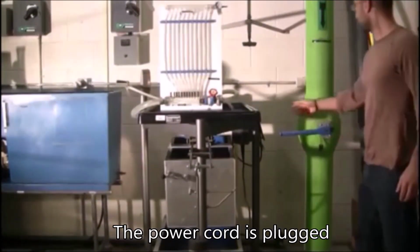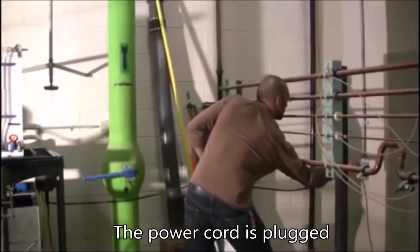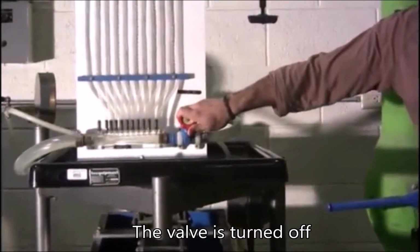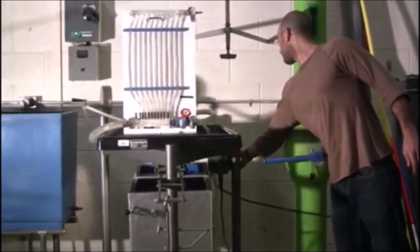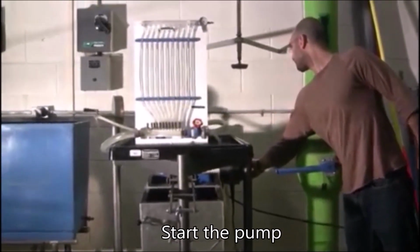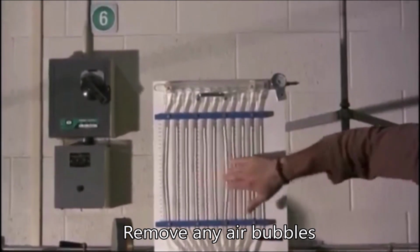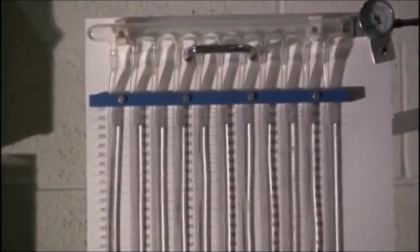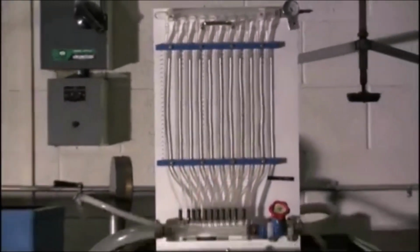Ensure that the power cord is plugged into the wall. Make sure the valve of the apparatus is turned off by turning the red valve clockwise. Start the pump. Remove any air bubbles from the manometers by tapping gently on the manometer tubes. Make sure that all the manometer readings are high and approximately equal. If not, seek help from the lab technician.